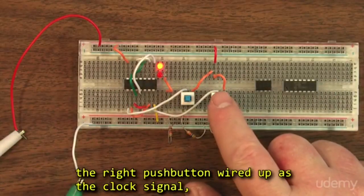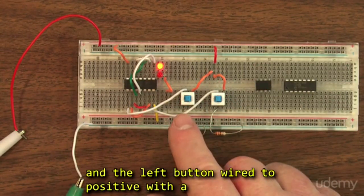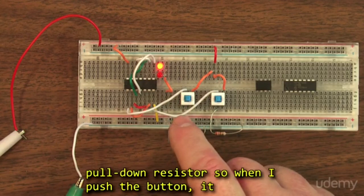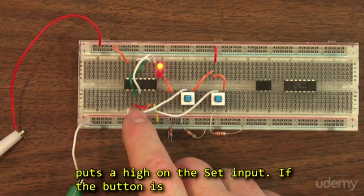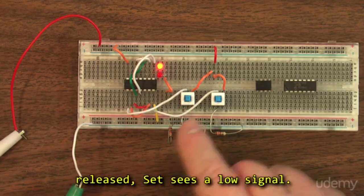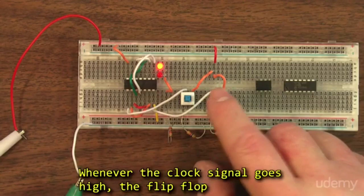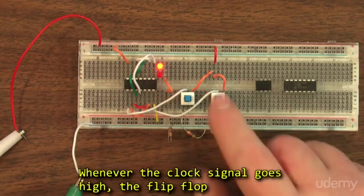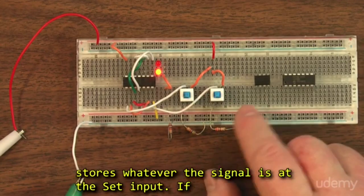I've got the right push button wired up as the clock signal and the left button wired to positive with a pull-down resistor. So when I push the button, it puts a high on the set input. And if the button is released, set sees a low signal. So whenever the clock signal goes high, the flip-flop stores whatever the signal is at the set input.